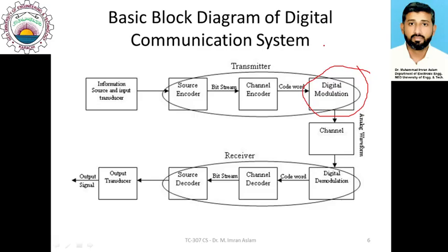Alternatively, in some cases, we need to have the sinusoidal carrier incorporated in the systems. In that case, we transmit the signal over relatively higher frequencies, so that becomes a band pass signal. That type of modulation scheme is generally named as digital band pass modulation, where you use a sinusoidal carrier to represent the digital information.